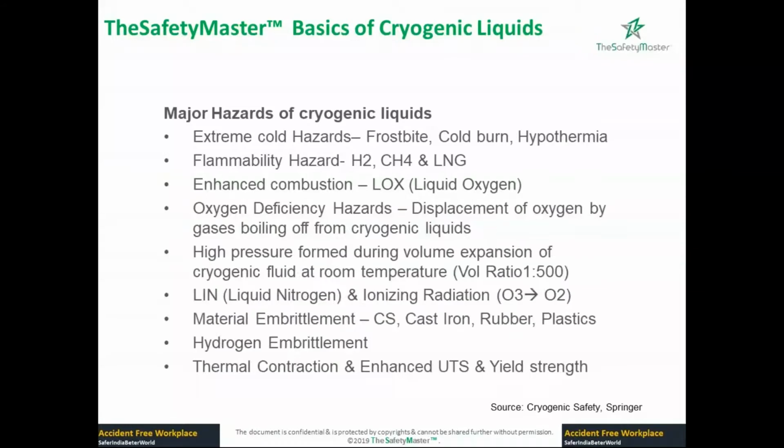You will start experiencing shortness of breath, and then you will fall unconscious. You'll feel dizziness, and as the oxygen level keeps dropping, you will go directly to coma and then to death. So this is a very serious hazard, oxygen deficiency hazard, particularly in enclosed or confined areas.